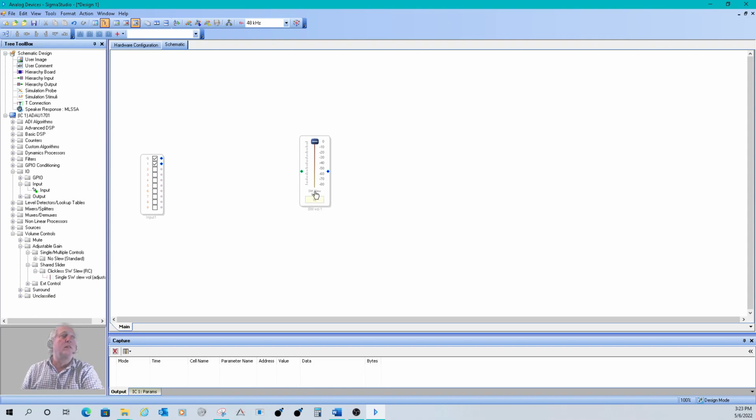That's what this number is in here, meaning when you make a change, it'll slowly step in very, very small steps to reach your final target volume with an RC curve, and make a much smoother volume change with no zipper noise. So it's a good thing to have.